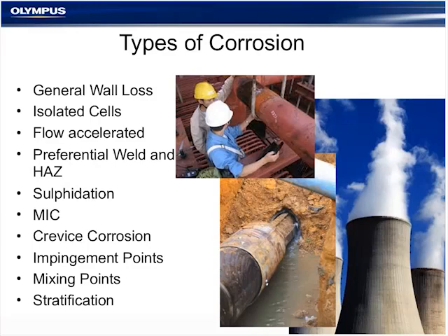However, you can also find instances of corrosion where you'll find isolated cells. And this is more common where you see, for instance, where water might separate from a process fluid, and that water might pool in a particular spot, and that would result in concentrated or uneven corrosion in a specific area. Similarly, flow-accelerated type corrosion, where the product itself is abrasive. It essentially acts as a sandpaper and is sanding the pipe from the inside out, and you're often going to find these isolated type corrosion, especially where there's some sort of focal point or some sort of bend in a pipe, something like that.